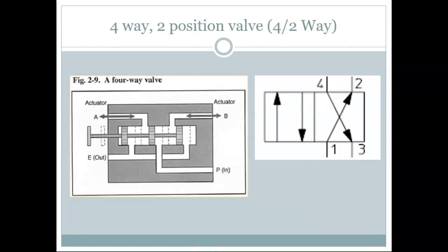So, 4-way, 2-position valve. What I want y'all to see is this little drawing right here, the one on the right. This is the very basics of drawing one of these valves. What you're seeing is a way to draw it so that it is understood by others who are going to be looking at these. So the very first thing you start off with are these boxes.